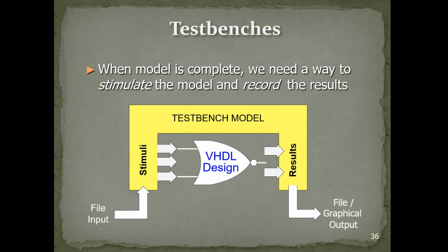And again, that can be done either in a graphical fashion, by just providing some input diagram with the mouse, or we can write a VHDL test bench specifically in the VHDL language, which is the more complicated one. But this is really the first key part of the process aside of learning VHDL itself. This is basically the thing which we are using to validate that our design works properly.